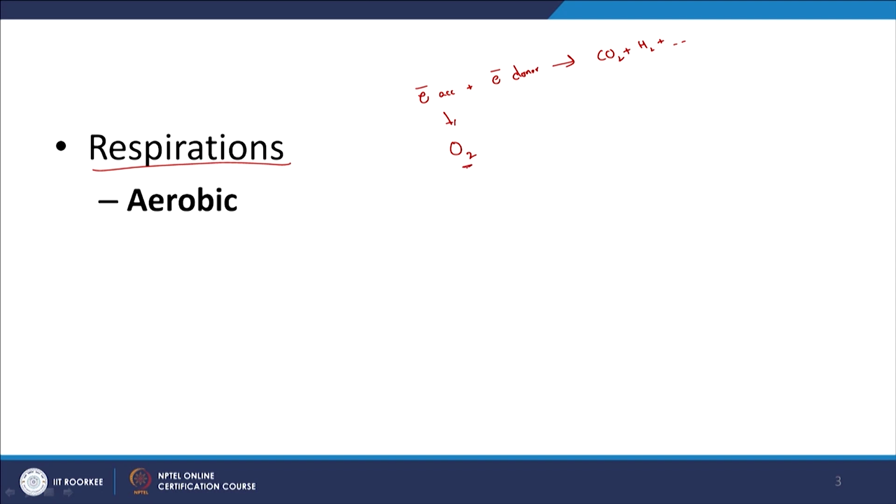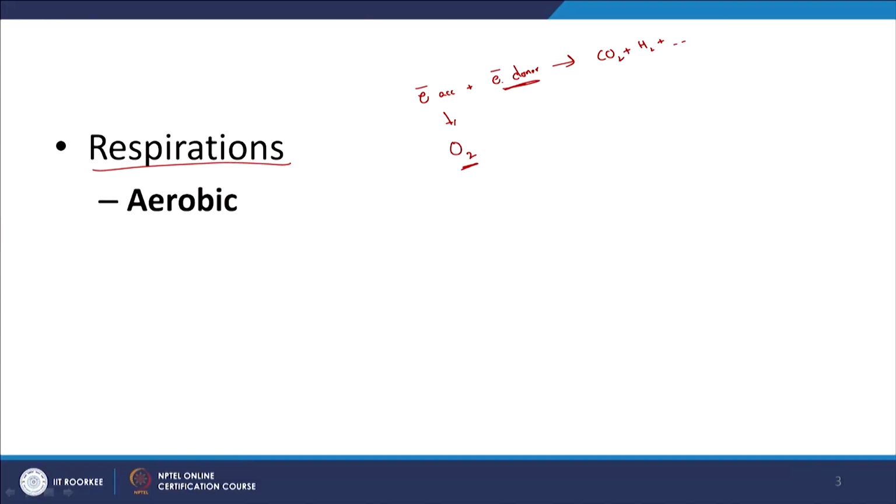So, again in aerobic process, let us say you are going to have oxygen, and then electron. If oxygen is present in your subsurface, or in the vadose zone and so on, then typically your electron donor is your contaminant, right, and this is what you are trying to remove, and oxygen is present. So how can you add oxygen? If it is in the vadose zone, there might be a considerable amount of oxygen present, or by bioventing, you can introduce some oxygen, you can pump oxygen and so on and so forth.